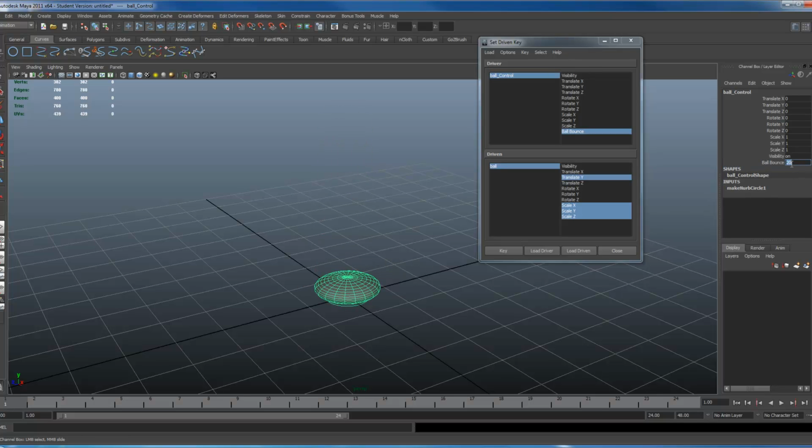So I believe I had decided to key in between each frame, so that'll be frame 10, so we'll deal with frame 5, and I keyed this. I had made this a scale of 0.5, 1.5, and 0.5. I'm going to deselect translate Y because I'm animating on translate Y. This time it's only X, Y, Z on scale. I key that. Frame 15, I had done the exact same thing.